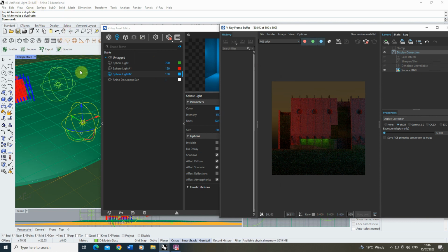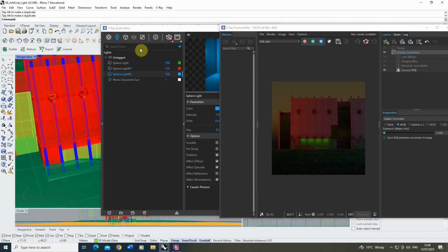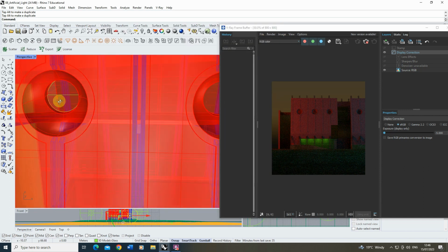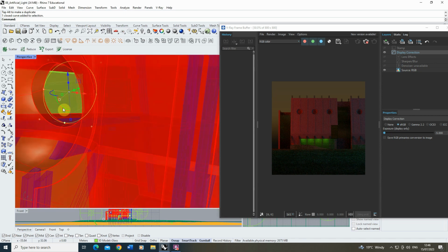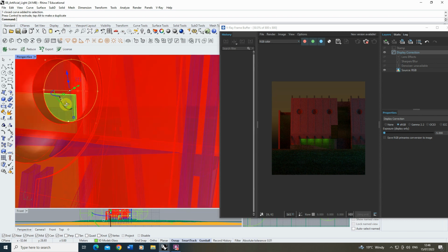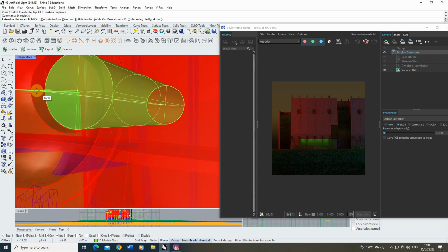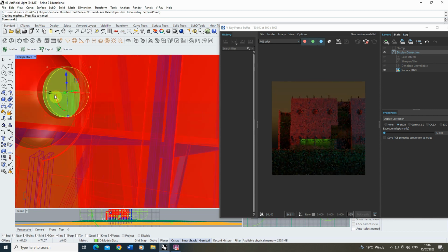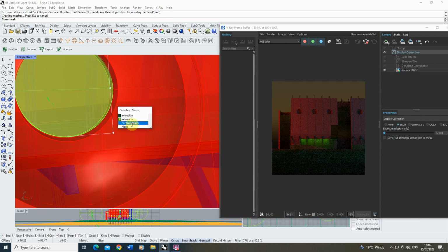Another thing we can play around with is actually creating emissive materials and creating objects that have light in the scene. So the way I'm going to do this is I've got a little window up here, and I've made a sort of curve in this window. Let's just rotate this a bit so it's parallel to that opening there, and then let's just extrude it out into an object. It doesn't really matter how big this is, but let's do it 0.1 like so.